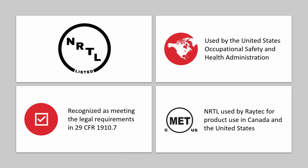So the last one we're going to look at is the system in place in Canada and the United States, which generally speaking do not base national compliance for hazardous area electrical products on the 60079 series of standards. Instead, a separate range of UL and CSA standards exist which the product must comply with.